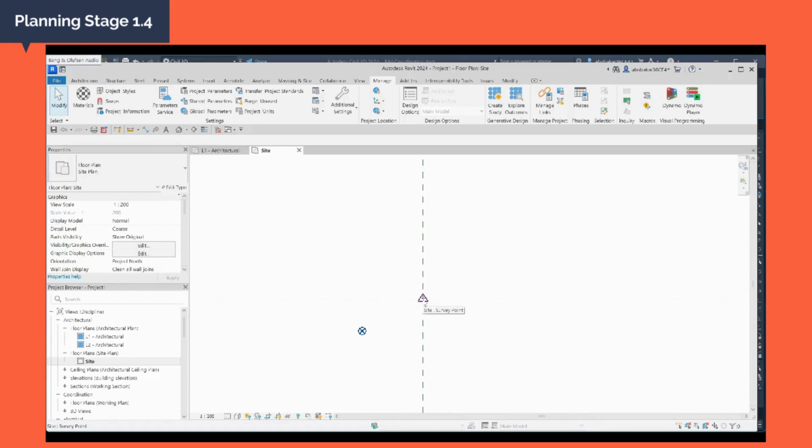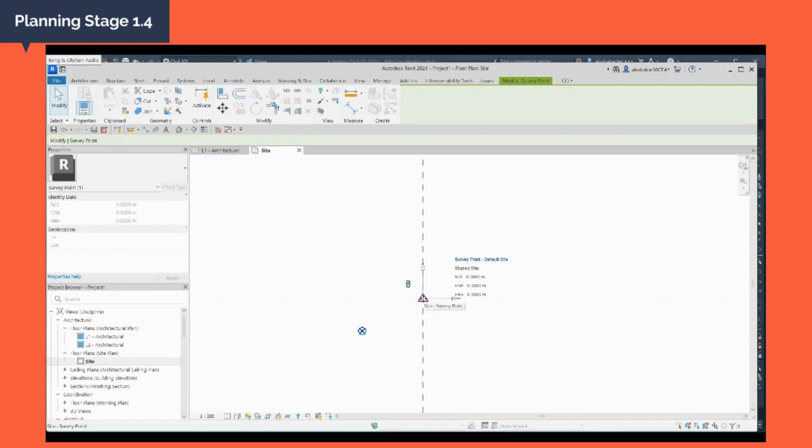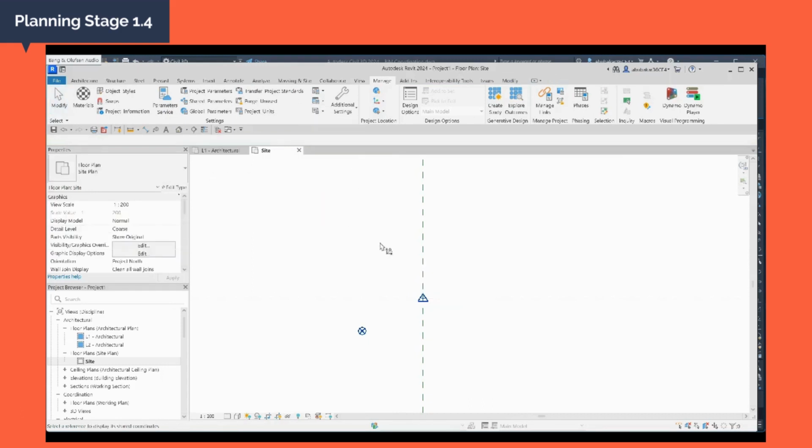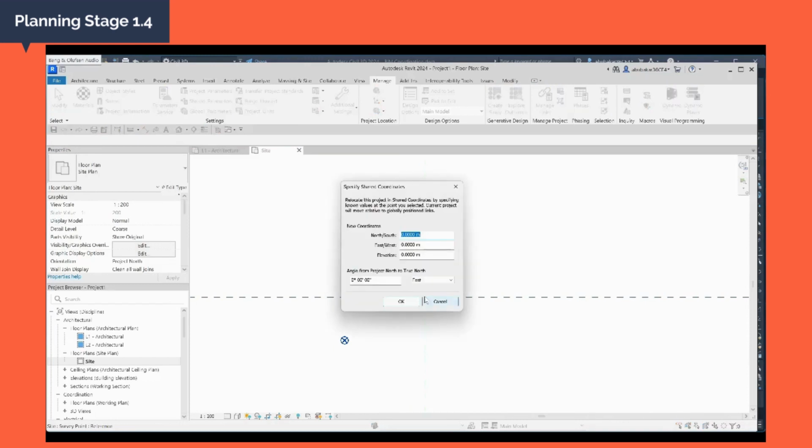So the next thing is to click on the surface point, and the first thing you do is to uncheck the point restrictions by clicking it off. So when you click it off, then you will coordinate from the Manage tab. You will use the coordinate information to set by specifying the coordinates at this point so that it will capture the exact reference from Civil 3D.